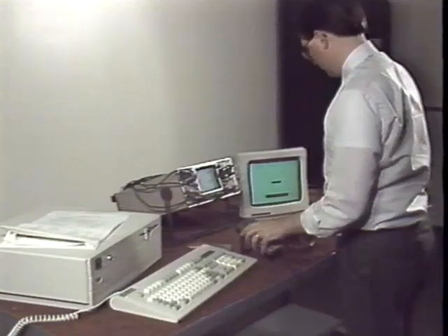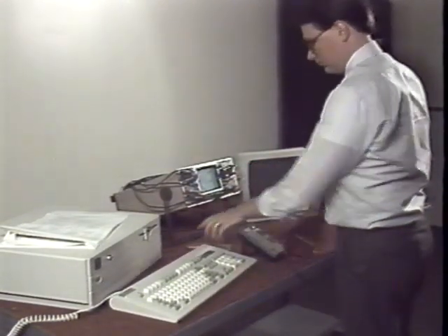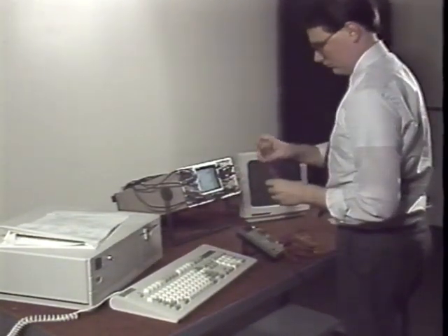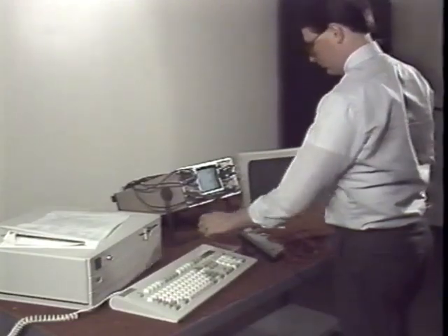Many of these same adjustments are present on color monitors, and they are done in the same way, so we will not repeat them. There are, however, some adjustments peculiar to color monitors, and we will discuss them next. When aligning a color monitor, follow the same safety precautions that you use with a monochrome set. Remove all jewelry, use an isolation transformer, and do not touch any of the high voltage components.